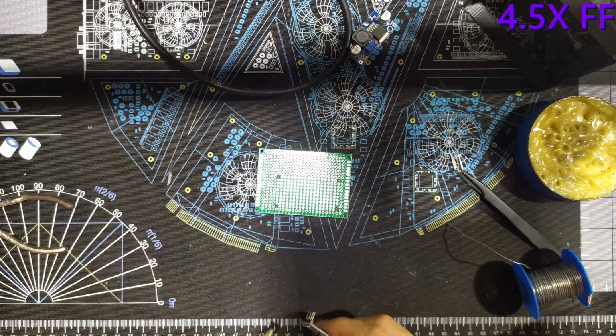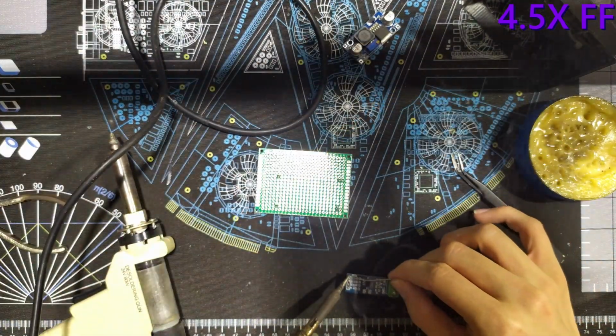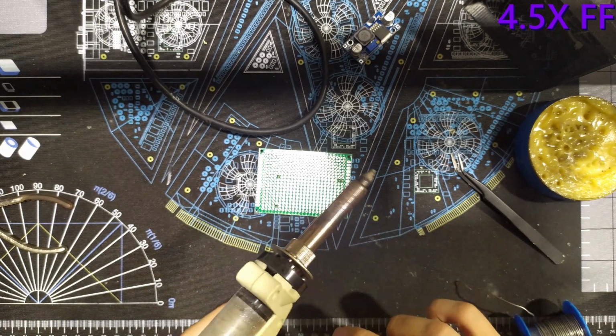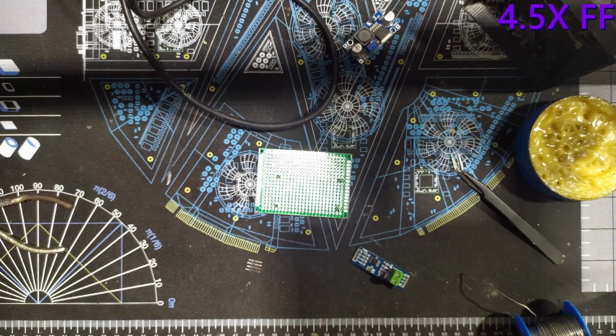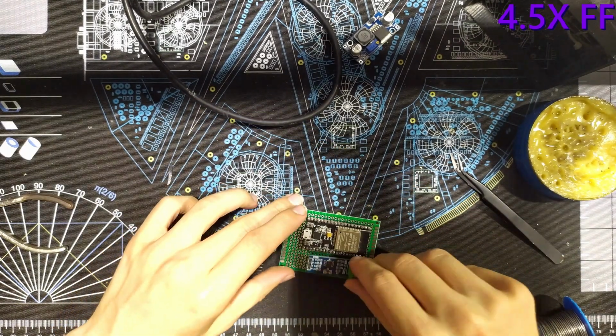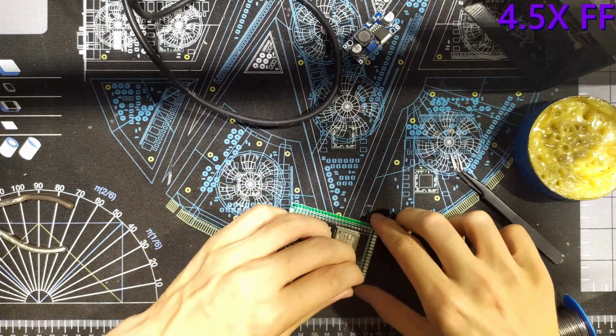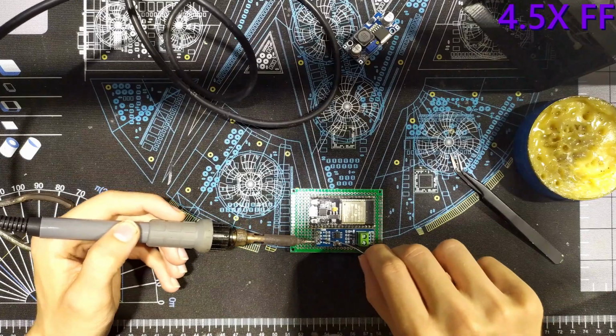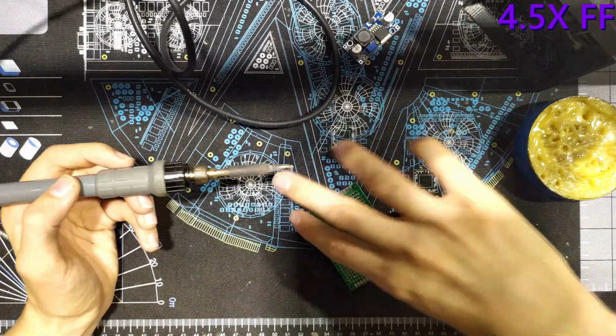Now it's time for the Modbus transceiver board, featuring a MAX485 chip as a middleman between the wallbox and the ESP32. Since the module I got from eBay was kinda crappy, I had to use my desoldering gun to remove the slightly angled pin headers so I could solder them back on straight. Otherwise the module wouldn't have been able to fit.